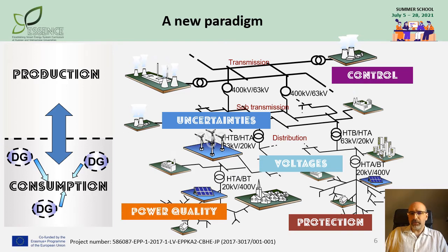Then, of course, there are issues about power quality. Typically, power electronic interfaces are creating some harmonics in the grid. And as well, if you have an issue about protection, you can blind the protection, but you can have as well undesired tripping. And that is creating some new issues about the reduction of power quality in the grid, both at power quality level, harmonics, voltage profile, sags, and so on, but as well at the continuity of service level.